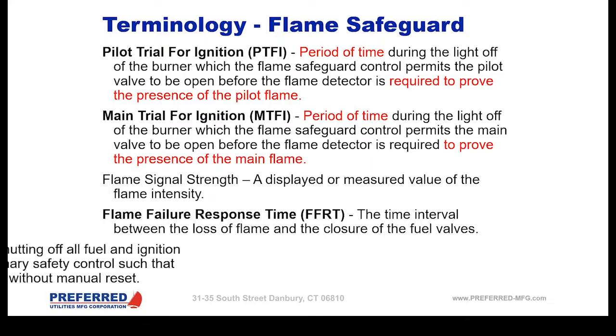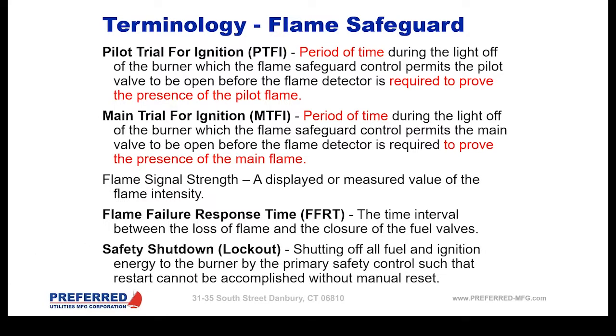Yeah, Steve, I wanted to point out with that Preferred 5004 M85 that you were showing earlier, your purge time and main trial for ignition time and flame failure response time are all set by dip switches that burn in after so many hours that the programmer is powered. Some of the other flame safeguard manufacturers have a lot of different permutations of controllers to buy for different timings, and we do them all with one. And the advantage is you only have to stock one flame safeguard module, and you only have to carry one on your truck for spares. That's a very huge selling point, and it's really great for service people because, again, you've got one control that does it all.